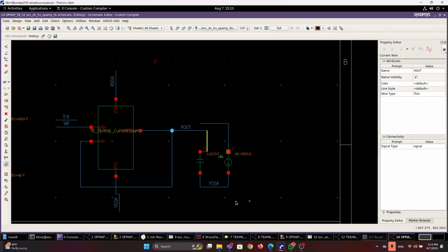You're able to supply 50 milliampere. So in this case, it's actually the ability of the op-amp to source current, right? Which means that it will be the PMOS problem. Yes. Okay. Usually for PMOS, what is the largest width that you can have?